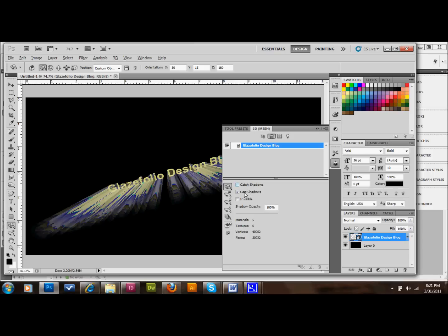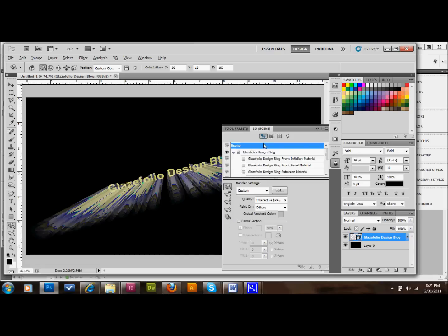as you'll see on your screen probably right now, actually, as you're doing this with me, if you are. You can see something similar to mine, and that just doesn't look good, does it? So what we'll do, sorry it's taking so long, we'll go to our first icon here up at the top, and we'll go to Quality, and we'll go to Ray Traced Draft. And that'll, just like in InDesign or something, we're viewing a lower quality image so that it'll go a little faster. Mine's going pretty slow anyway, but when you go to Ray Traced Draft, it'll show you a draft of what it should look like in its final appearance if you were to save it out.